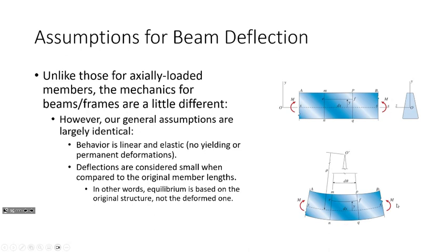There are some problems in structural engineering where we have to consider large displacement theory. A good example of those are wind and earthquakes, okay? So for example, you have a building that has a very large vertical load and suddenly it gets hit by wind or it gets hit by earthquake and that load gets shifted over, and so the exterior columns, for example, that are keeping the building upright laterally have to consider those second order effects. But those are one component in a vast structural system that most of those elements don't have to worry about that, okay? There are provisions in design land where we can handle second order effects a lot easier, but I just mentioned that to sort of explain what small deflection theory versus large deflection theory means.